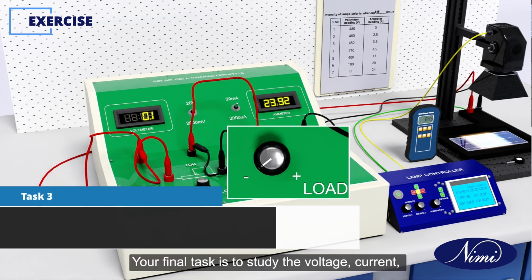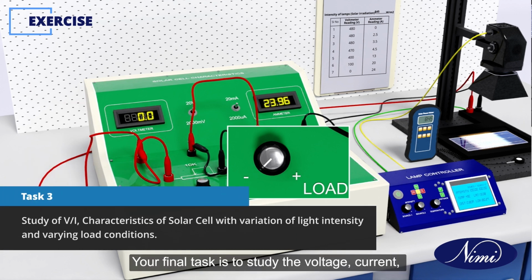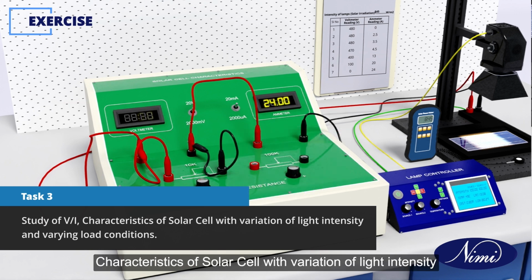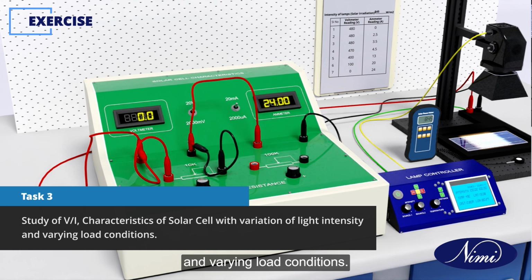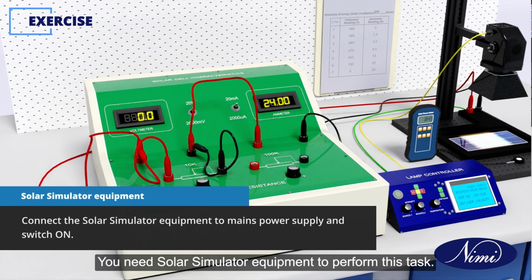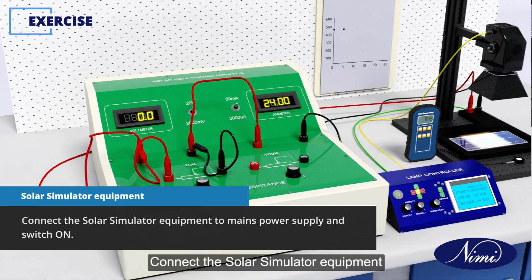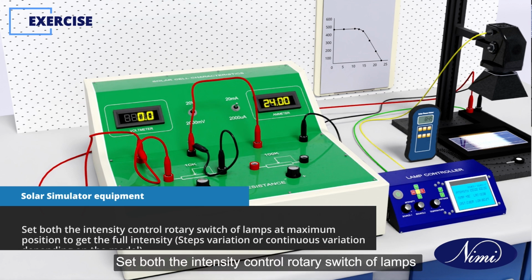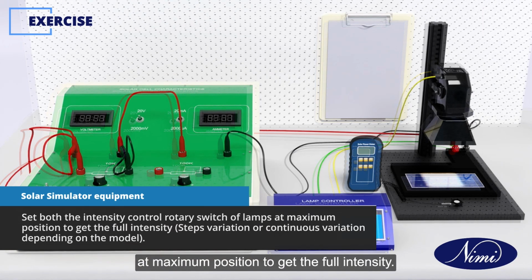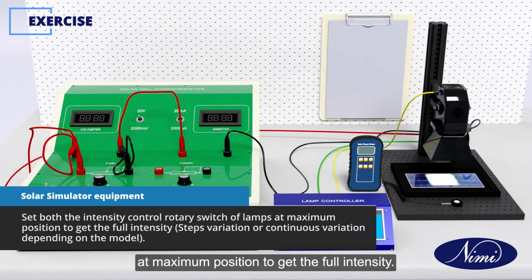Your final task is to study the voltage, current and characteristics of a solar cell with variation of light intensity and varying load conditions. You need the solar simulator equipment to perform this task. Connect the solar simulator equipment to the mains power supply and switch on. Set the intensity control rotary switch of the lamps at maximum position to get the full intensity.